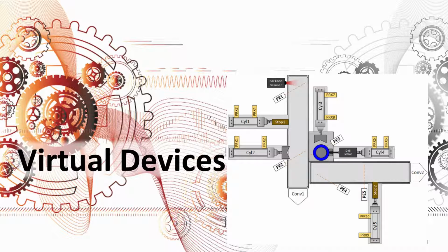And we've, for the most part, stuck to that ratio and quantity of I/O in all of our manuals, because when you're working with licensed switches, when you get beyond 6 in and 4 out, it gets pretty tough. It becomes relatively difficult to keep track of which switch is which device input and which light is which device output.